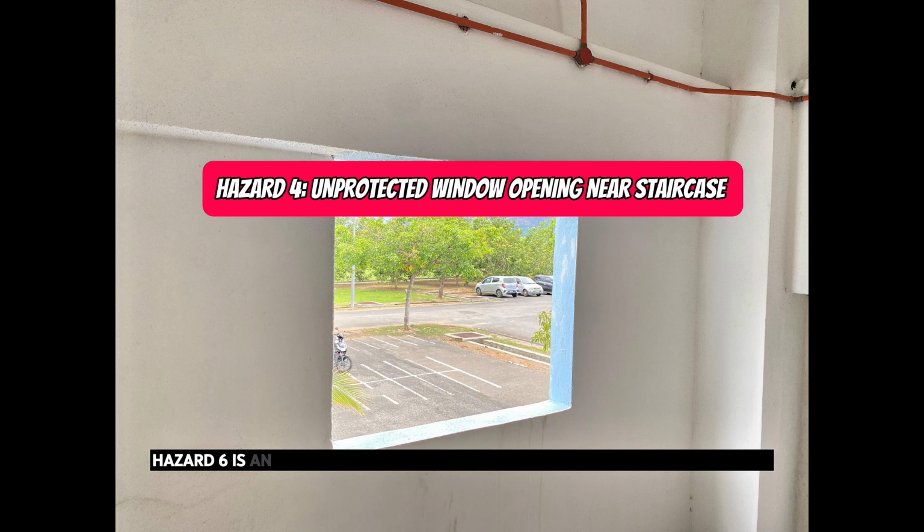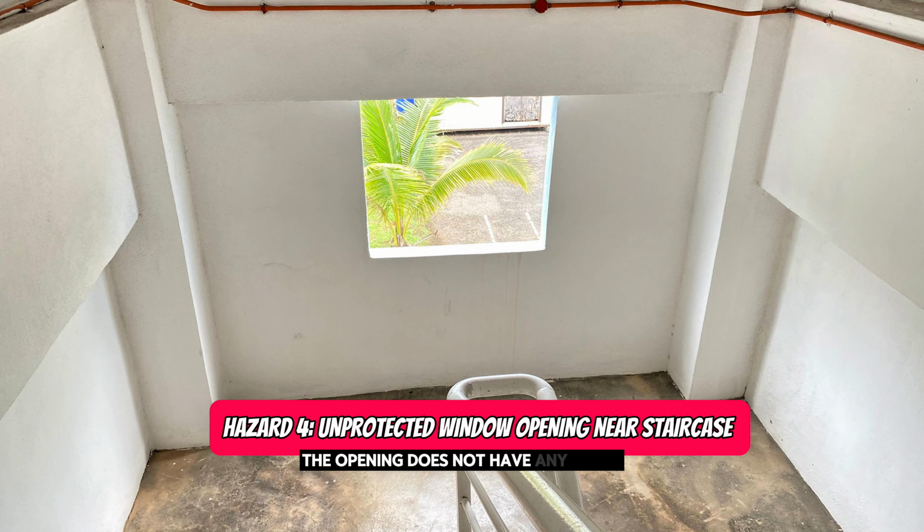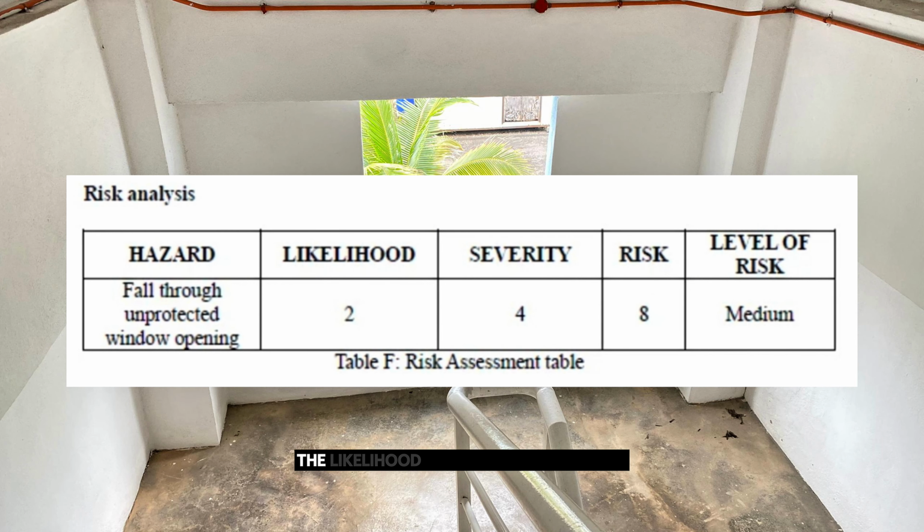Hazard 6 is an unprotected window opening located near the staircase. The opening does not have any grill, guardrail, or safety barrier. If a person loses balance while using the stairs, there is a possibility of falling through the opening, which may result in serious injuries. According to the risk assessment, the likelihood is 2 and the severity is 4, resulting in a risk score of 8, which is also classified as a medium risk.